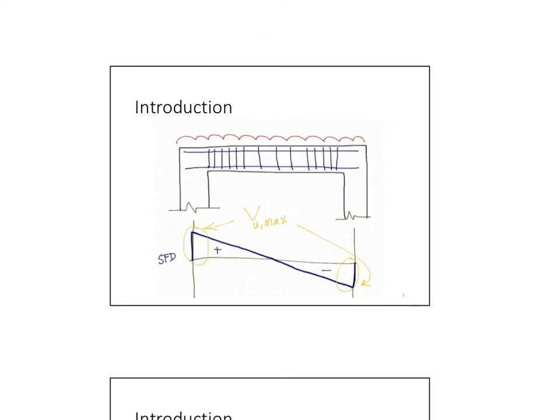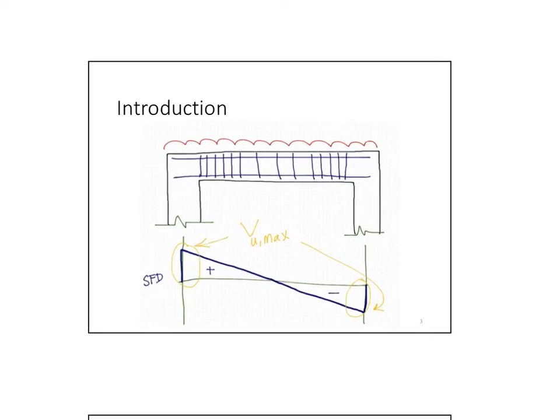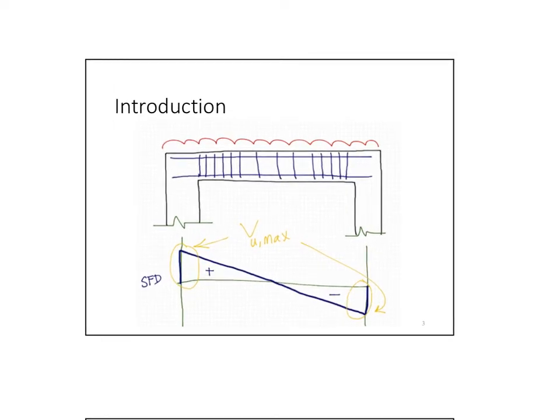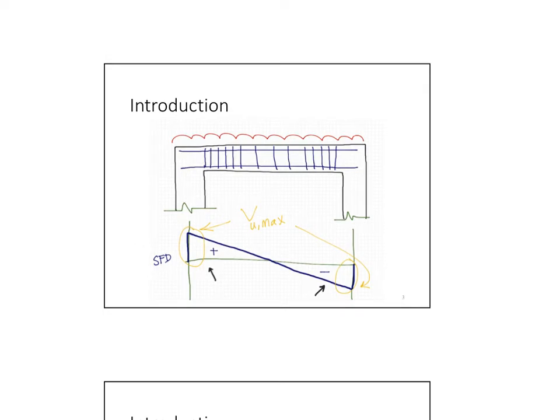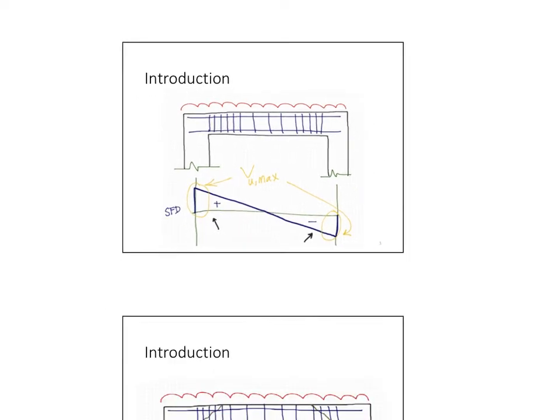Now, looking at a simply supported beam on two columns, as in the figure here, from structural analysis courses, you remember that where the shear is maximum is towards the support, right? These could be different by different loading configurations, but what we're looking at here is for a simply supported beam, the maximum shear happens very close to the support.